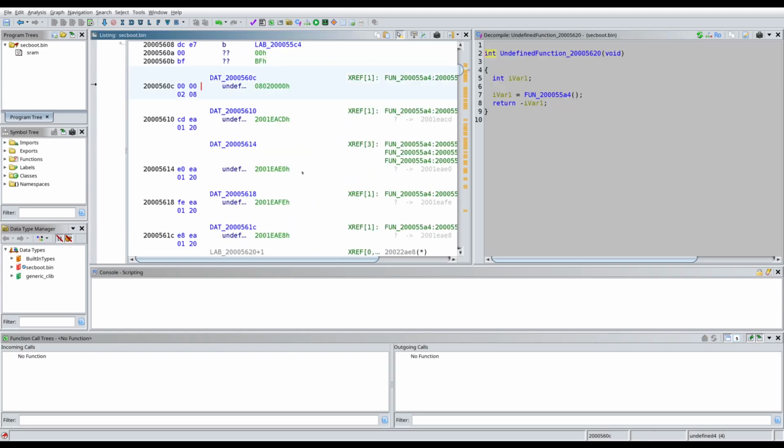And here's one such reference. As you can see, this is a pointer to a different memory range. And this, 08, is actually the memory range of the internal flash. And I happen to know that 802 is where application firmware will reside, the application, once it's been decrypted. 0 here would be where the actual boot is. They boot off the internal flash. And so by knowing this, that this is how it's addressed, if that's how they access the keys, we're not going to get them into our nice little exploitable RAM. So we need to do something else.